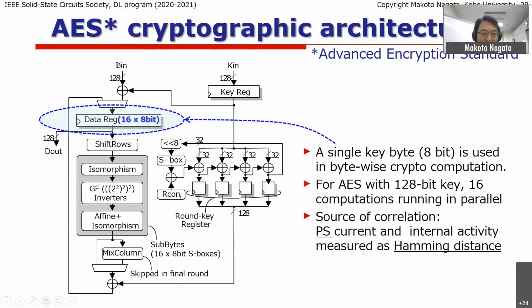In this case, the plain text is input, and the output is decrypted data. By using this data path, and normally this is a kind of loop architecture. That means first line, first processing, and the data is coming back to the input again, and the second, and the third, and so forth. Often these types of architecture use 12 clock cycles or 12 loops internally in the processing of the AES.